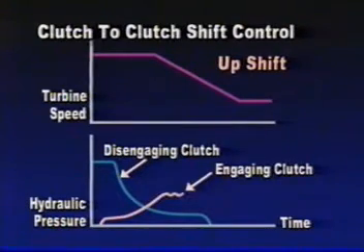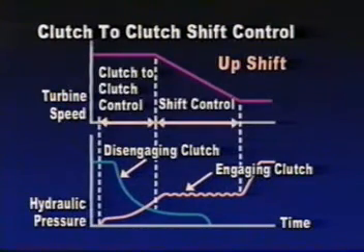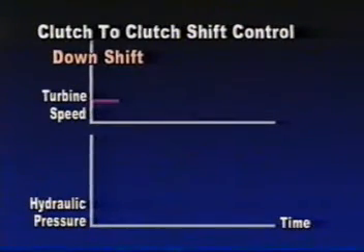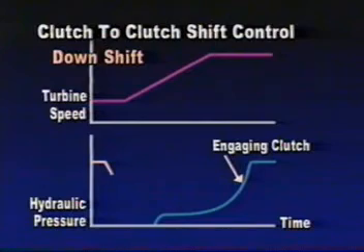TCM calculates the appropriate oil pressure, receiving speed signals of input and output shaft. Output signals are transmitted to 4 or 5 solenoid valves, depending on the 4-speed or 5-speed automatic transaxles respectively. Then, shift is performed by controlling clutch or brake of release and connection simultaneously.